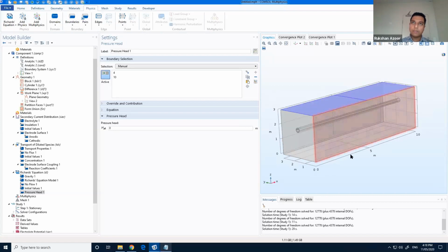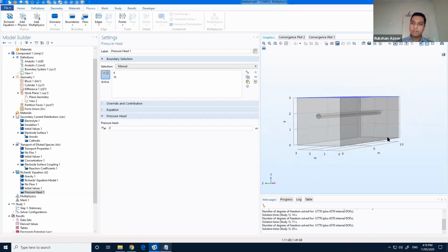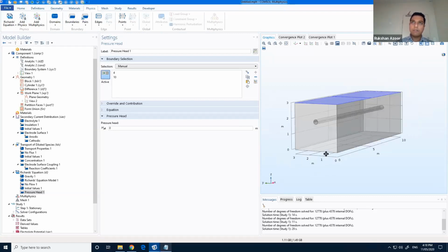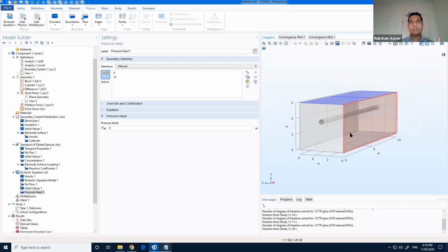However, there'll be gravity effects. Because it's a steady state, we are not solving any moisture flow. We are not going to couple it to corrosion because it's a bit more complex, that we'll do later on. What we are trying to solve is just giving a gravity hydrostatic pressure head based on our surface suction and the corresponding saturation at that suction using the Van Genuchten water retention curve.